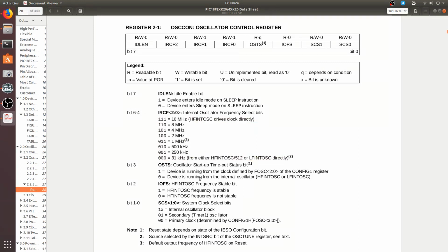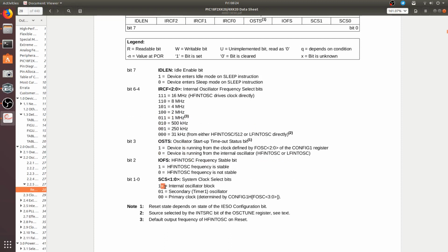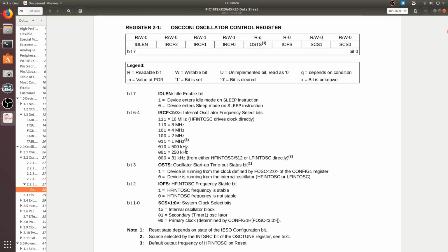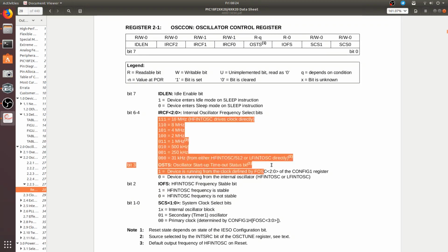You will see many times when you look at a register, for instance, there is an X. When it's an X, it means that if the other bits are those specified values, then this is don't care. So if the first bit is a 1, the second bit for this sub-register would be a don't care. It doesn't matter. If these are 0, you can clearly see it can be either a 0 or a 1. So with these 3, all possible combinations of those 2 bits have been denoted. But here, everything is clearly laid out.